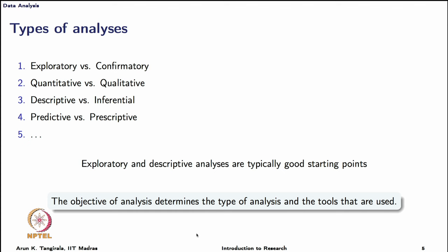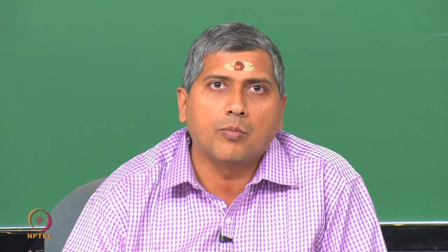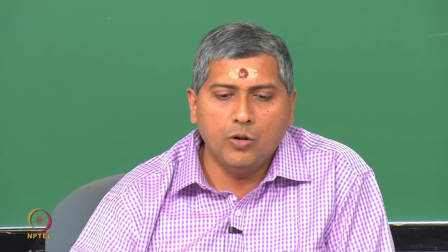Then you have predictive versus prescriptive. Predictive analysis is about asking where the process is heading based on data, and this is very useful in many applications. Whereas prescriptive is about asking why something has happened. So, you have looked at the data either as a doctor or as an engineer or even as an econometrician, and you looked at market data and suddenly there has been a crash, and you are asking, well, why did this crash occur, or why did a particular fault occur in a process. And then you are of course going to suggest how to prevent this. So, there is going to be a diagnosis and remedial thing involved in prescriptive analysis.